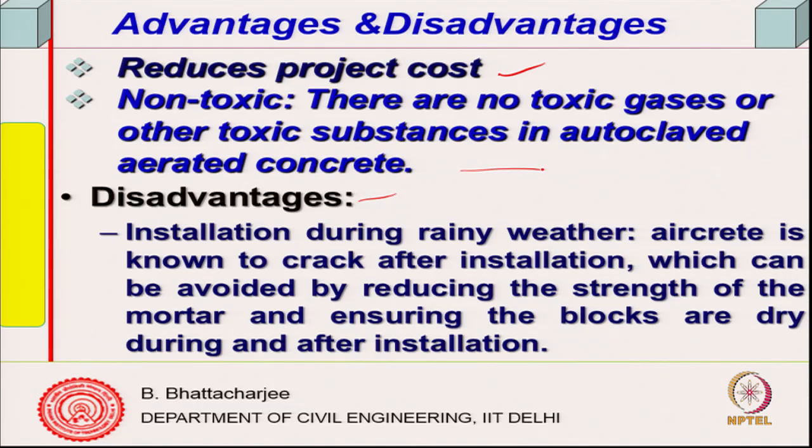Disadvantages: if you have to install during rainy weather, this is known to crack after installation, because moisture will penetrate, and differential moisture condition might result in cracks. So, reduce the strength of the mortar and ensure blocks are dry during and after installation.